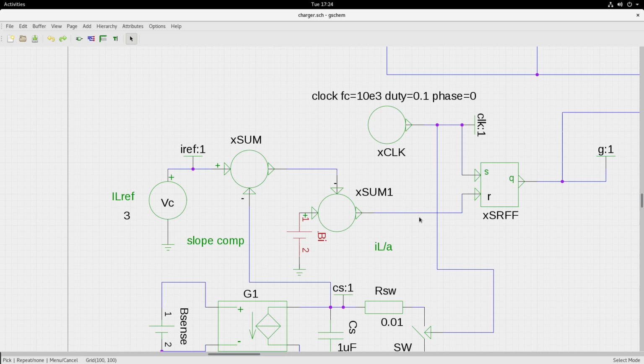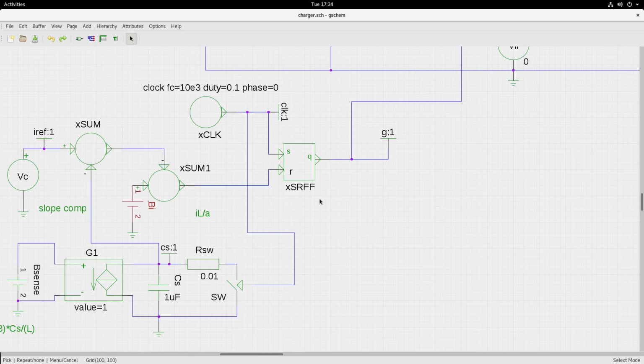We had put a comparator here with a minus and plus with an inversion, and this comparator block I have removed and did a sign change here itself, minus and plus. The inversion caused by the comparator is brought forward, and I have inverted the sign here because there is a Schmitt comparator at the input to the SR latch itself. So that is the only change.